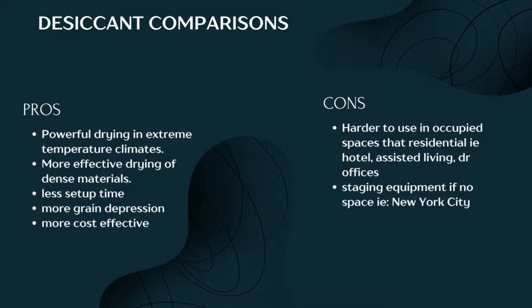The desiccant will put out anywhere from 118 degrees to 160 degrees, depending on which desiccant you're using. So they do help add heat, but you still got to get those surfaces warm for them to be able to evaporate moisture out of them. So sometimes even with the desiccant, you may have to add additional heat. Or some people may just put an additional desiccant in, but usually if you've got enough drying capacity, you probably would want to just add heat.